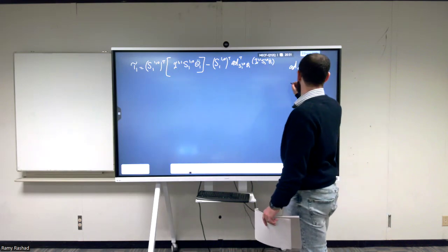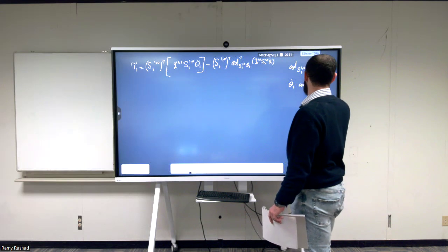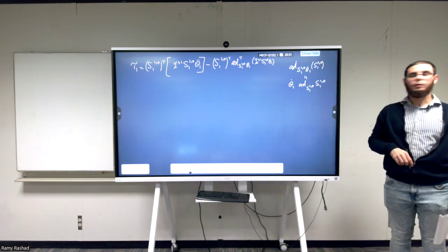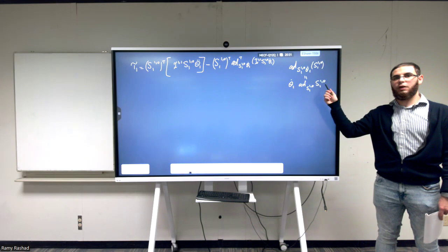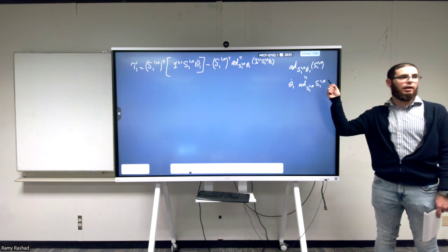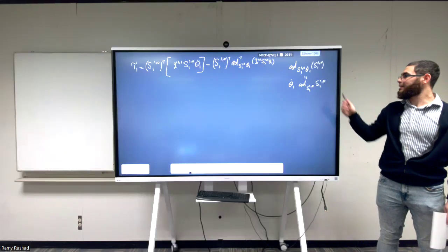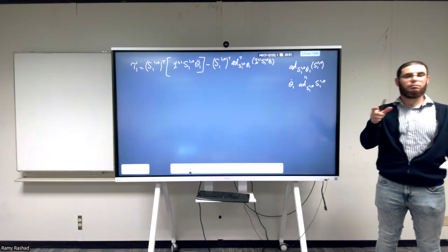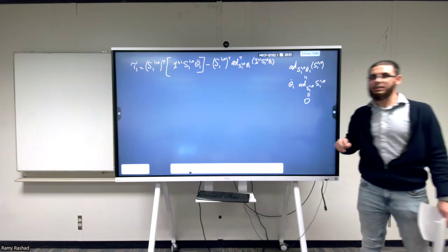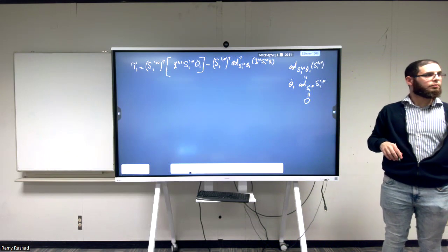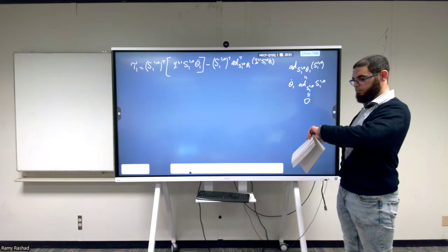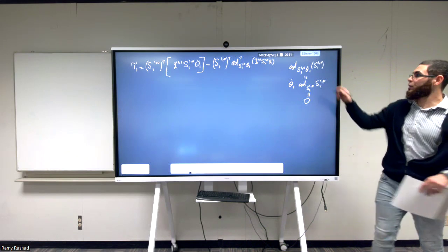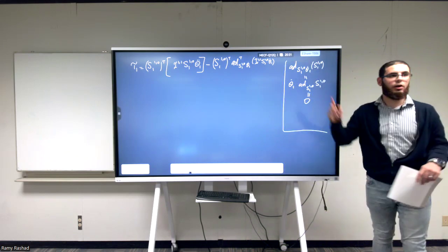So this is equal to theta 1 dot multiplied by the adjoint of S10 multiplied by S10, like that. So this is the adjoint of some twist with itself. You can prove for yourself that the adjoint of two twists that are the same will give 0. It's very easy to check. If there's time in the end, I can show you very quickly how it looks. It will just take a couple of steps. But for now, just leave it like that so that we can continue.